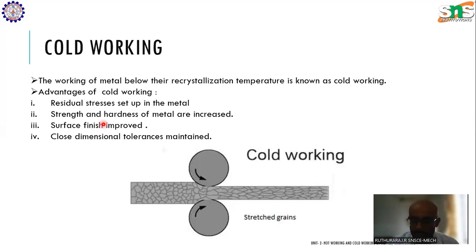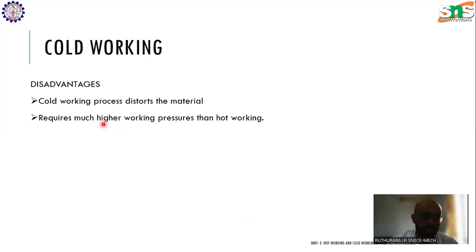And the major advantage of this cold working process is that surface finish is improved. Since there is no deposition of carbon because of the application of heat, the surface is smoother compared to the hot working process. That's a major advantage of this cold working process.